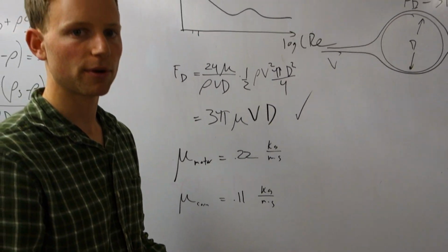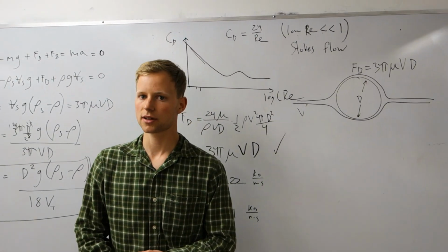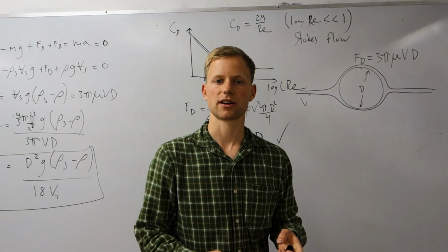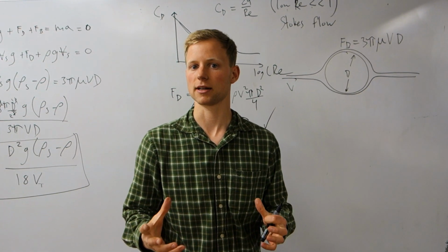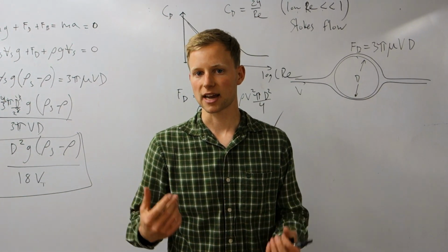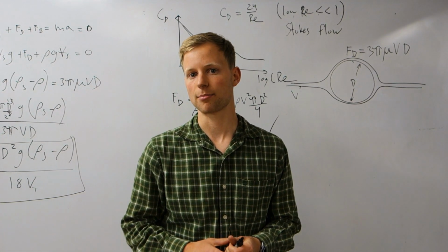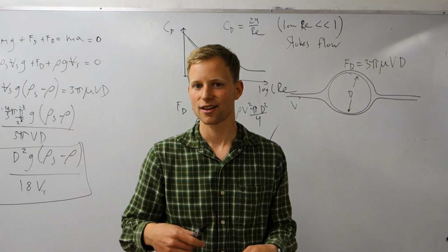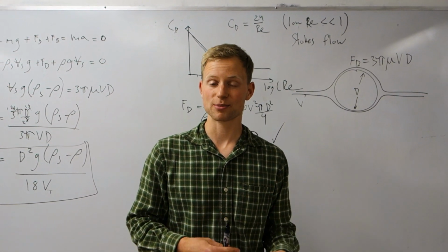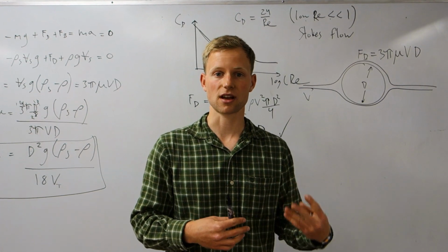So in summary, this lab was about reviewing Euler equations using the viscosity turntable, where we derived the free surface of the spinning fluid in a cylinder. And then we used the Buckingham pi theorem to find the relevant pi groups for our sphere dropping in a fluid. And then we used those pi groups and a pre-existing relationship to solve for the viscosity.